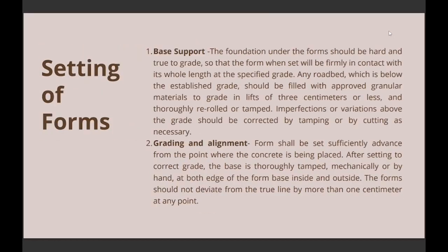Setting of forms. Number one, base support. The foundation under the form should be hard and true to grade so that the form, when set, will be firmly in contact for its whole length at the specified grade. And number two is grading and alignment.